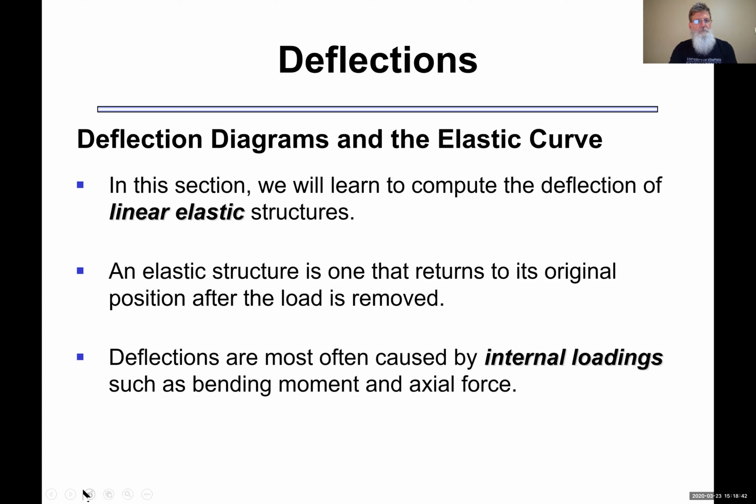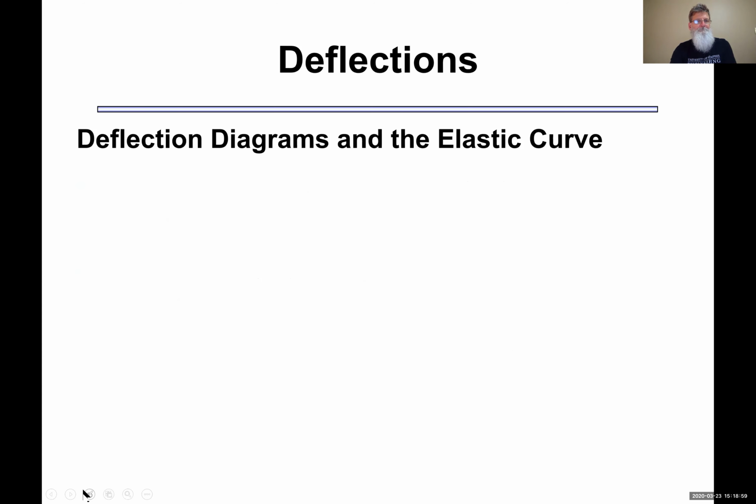So deflections are mostly caused by internal loadings. And in our case, we spent some time this semester already talking about axial force, shear force, and bending moment. And we'll find that axial force, shear force, and bending moment are the primary drivers of deflections in our structures.